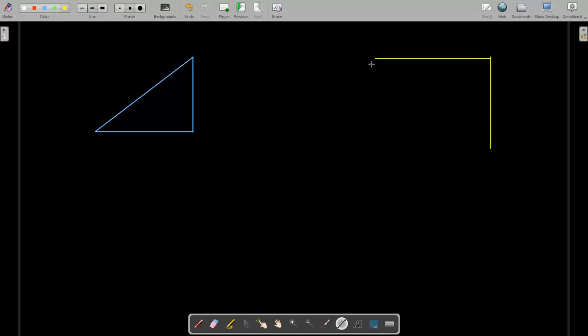For inlet the flow is radial, so there is only one triangle and only one angle, alpha 1. And at outlet the flow is also radial because it is a reaction turbine. So at outlet the flow is like this. Suppose I am drawing a turbine blade here.